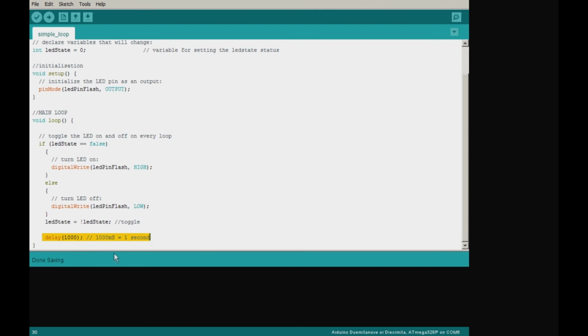We're not going to proceed and do any more instructions. We're just going to be waiting for 1 second to elapse. Once it's elapsed, then the code can all start again in the main loop. So in other words, think of it this way: all this code happens very, very quickly, whoosh, straight through, very fast, maximum clock speed, and then you get to this bit, and then the microcontroller will effectively stop and wait and not proceed any further until 1 second has elapsed.